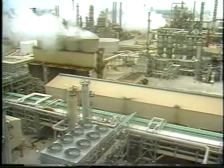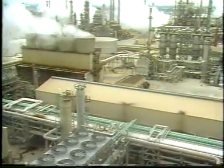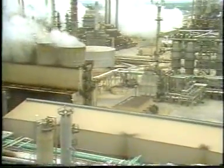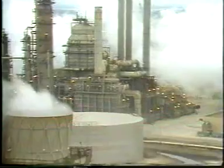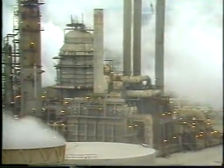The operation of a distillation column requires auxiliary equipment such as furnaces, reboilers, and condensers. This auxiliary equipment is needed to vaporize hydrocarbons and provide a cooled, liquid reflux. A furnace uses burners to heat the feed as it passes through a series of tubes. The tubes absorb heat in two different ways. First, the tubes at the bottom of the furnace receive direct rays of heat from the burners. Then the gases and vapors formed by burning fuel and air are channeled into the top section of the furnace